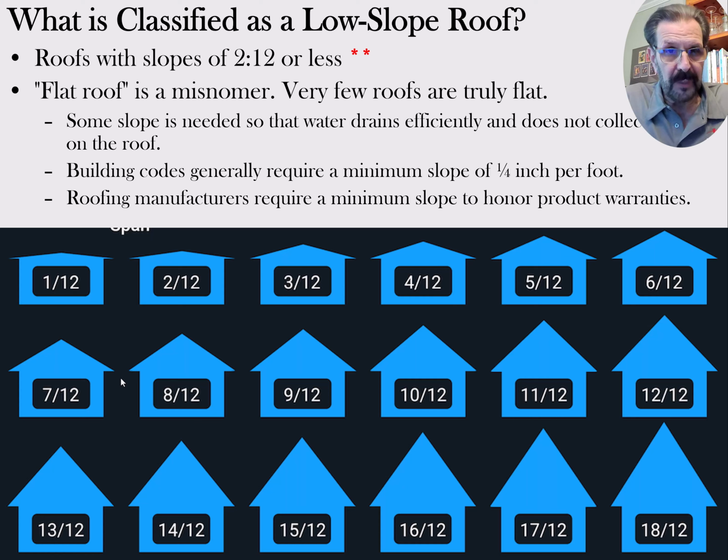We have to choose which roofing material depending on what the slope is. You can't use shingles on a low slope roof. And generally, we don't use membranes, solid membranes, too much on steeper slope roofs. So there's this crossover zone where sometimes people try to use shingles on lower slope roofs, and without much success. It's problematic. And sometimes they try to use membranes where they probably should use shingles or tiles or slate panels and that sort of thing.